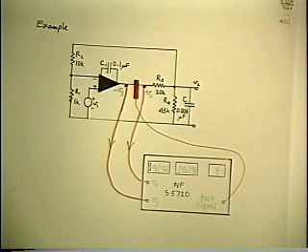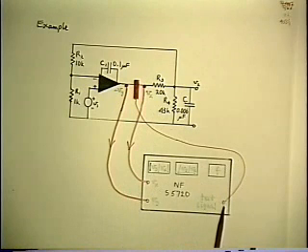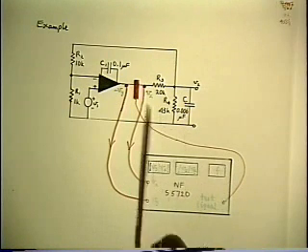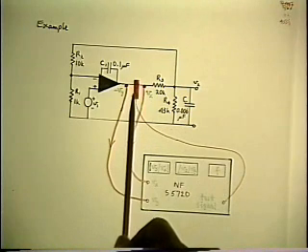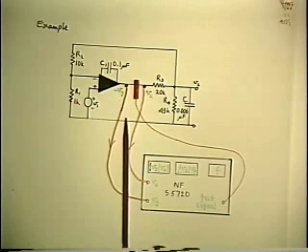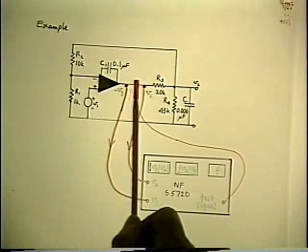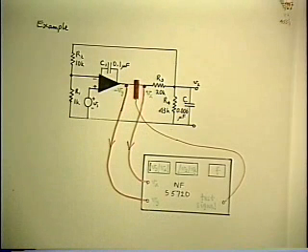But any real transformer works backwards. So what we're doing is plugging the probe into a signal source. And you clip it around the wire, and it works as a one-turn secondary isolation injection transformer. And it injects a voltage into the piece of wire.